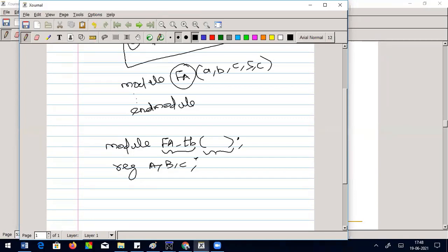For what reason? Then alone any change in the input will immediately get reflected in my design. Otherwise, it takes the next clock cycle to update. So that's the reason for all inputs, we make them a wire.